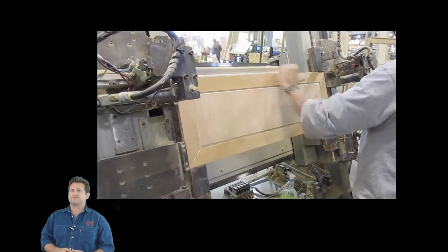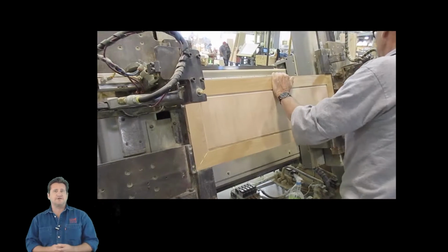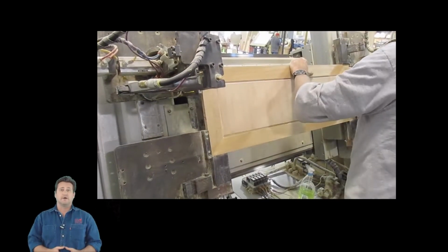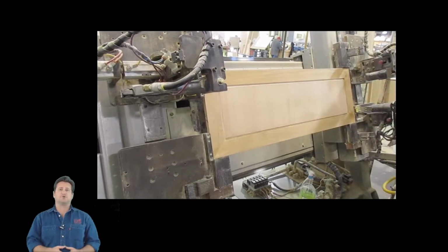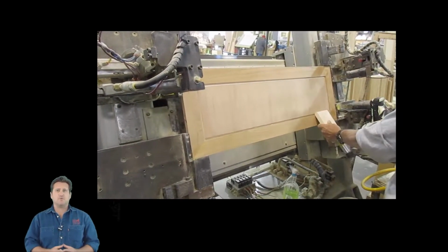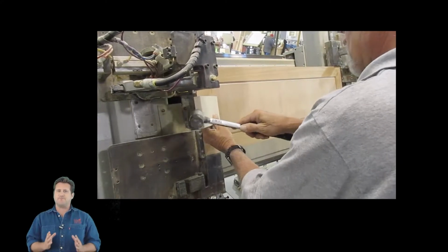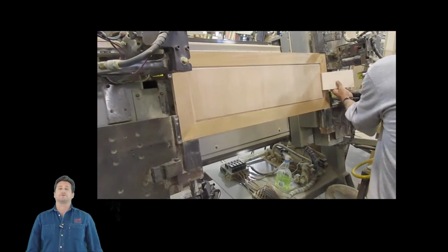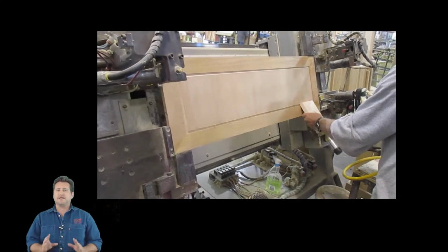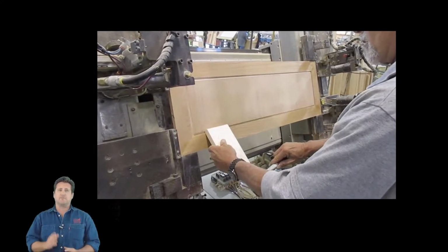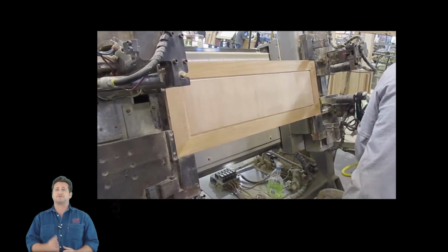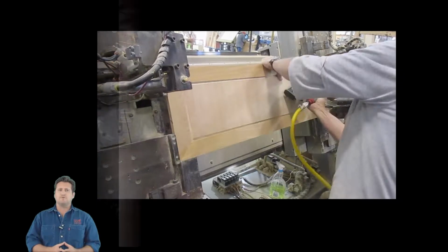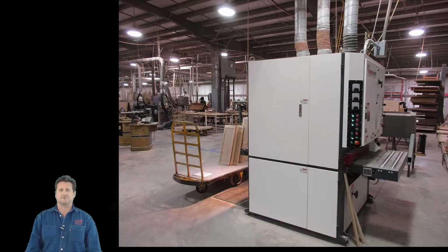Now, this clamp applies several tons of force while squeezing the door into a perfectly square and tightly aligned cabinet door, and this clamping process is being shown now. Because the coped rail and stile are machined to form a very tight-fitting joint, the clamp assures that the door is perfectly square. The joints and inset panel are now pinned from the back with 1/2 inch brads to prevent panel movement.